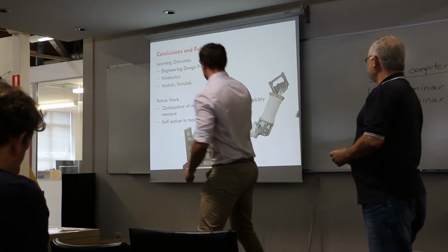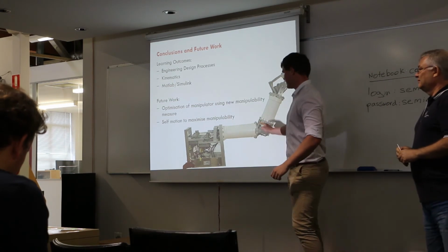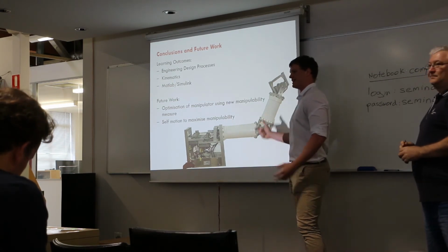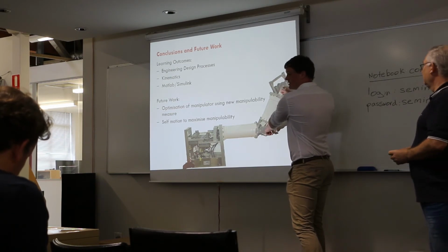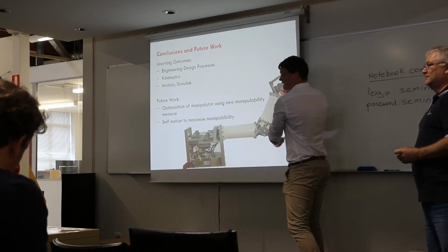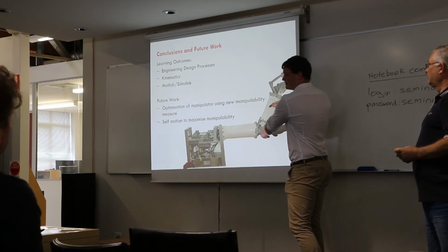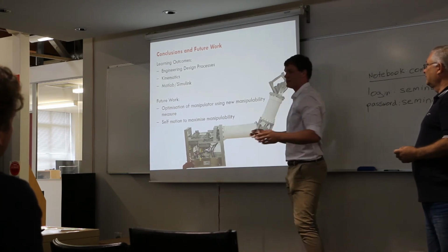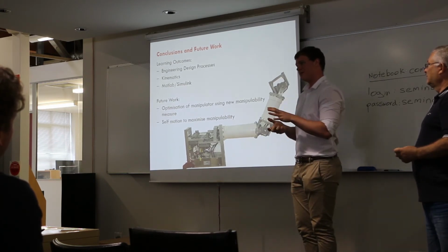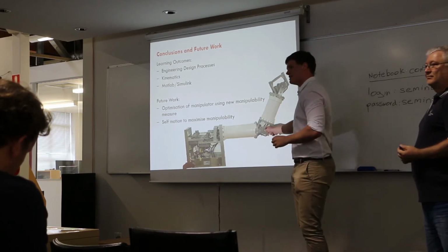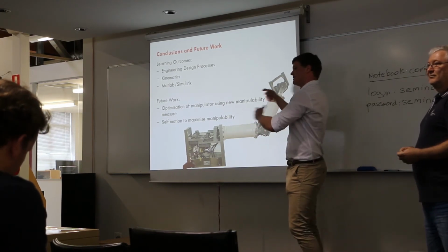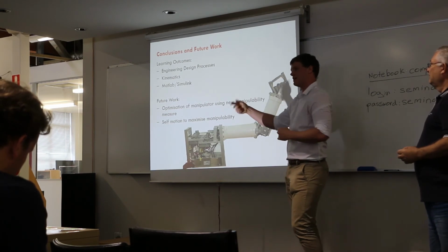Yeah, so they're all here. When you have the actuators here, it's really heavy. So this actuator has to lift around this one. And there's two here and two here. So having them in the base allows you to minimize the length to diameter ratio. You can make the diameter smaller because you don't have the big actuators in there, which have to lift the weight distributed away from all the other actuators.